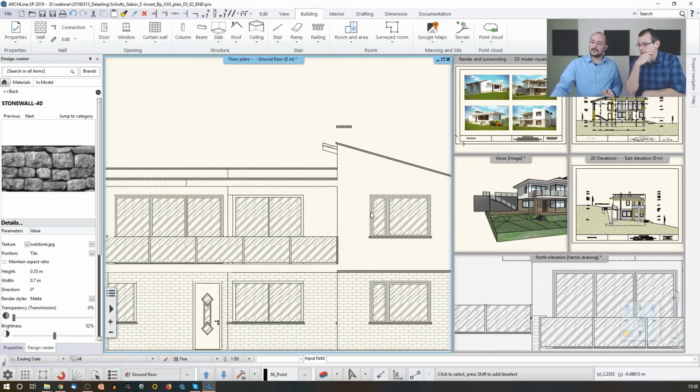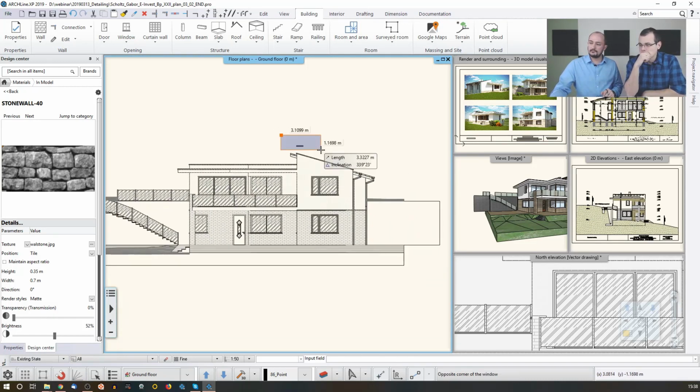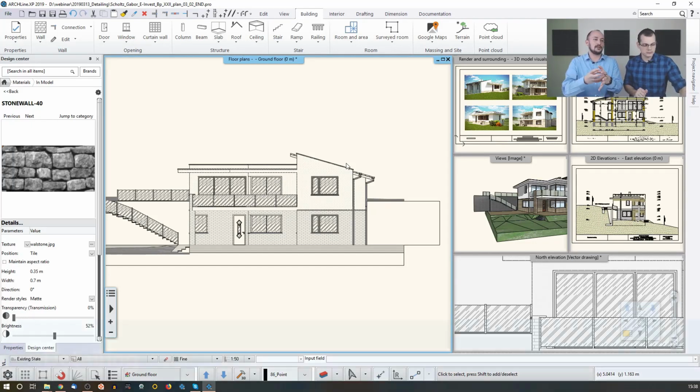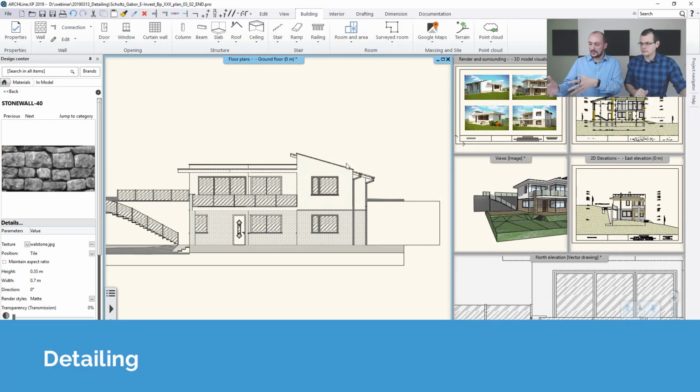So this way you can modify this in any sort of way. You can remove things, you can add things, just the way your project needs. But remember, this drawing is already a detached and unlinked copy of the original dynamic content. The original dynamic content will be updated, but this unlinked copy won't be in any sort of connection to the rest of the drawing.